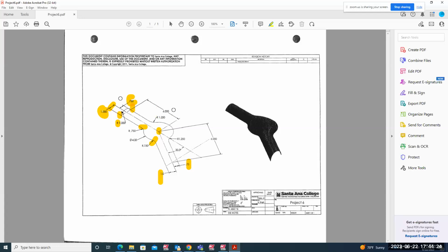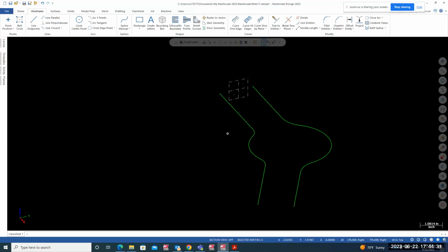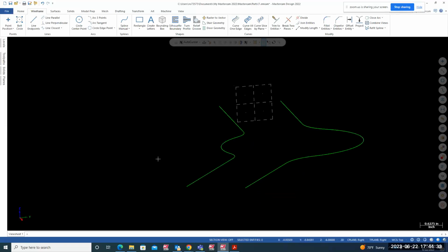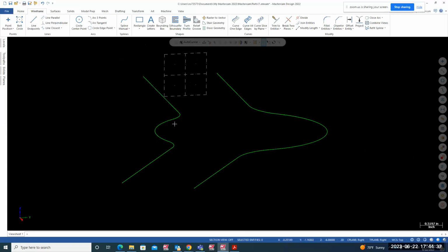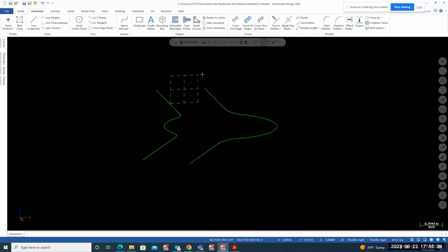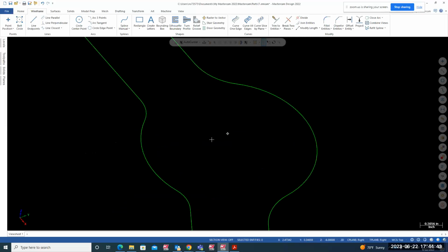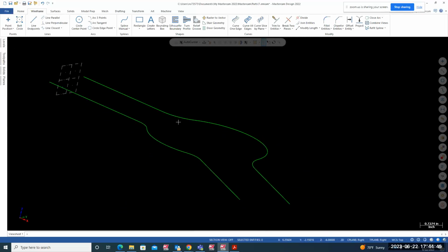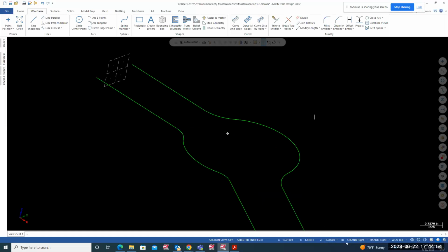That's why we're going to create that arc with the radius 1 inch. All right, so we are good. You can go construction plane right if you want to see that, but I'll just use my mouse and stay over here somewhere. Yes, I'm in right plane now. Look at this construction plane right. Z is minus 6.